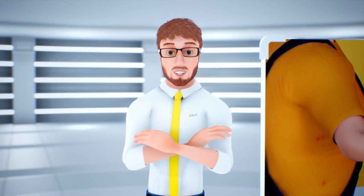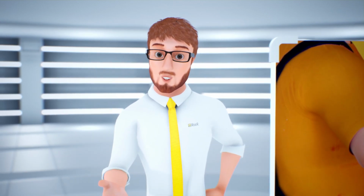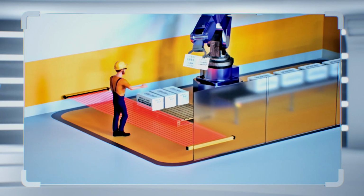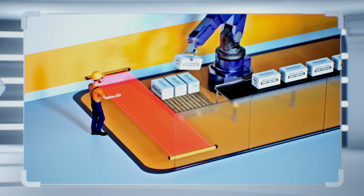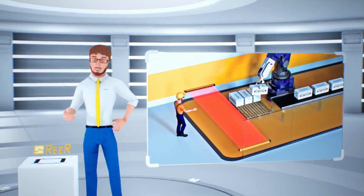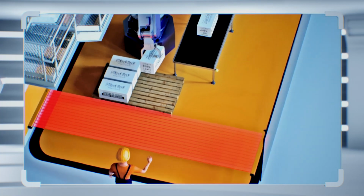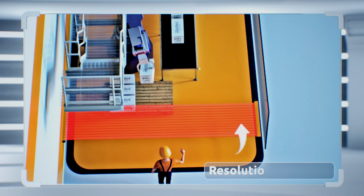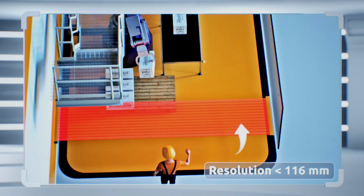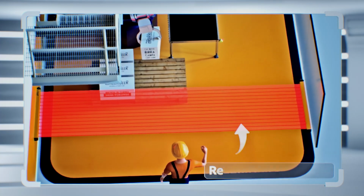When it is necessary to verify the operator's presence in a dangerous area, for example in front of a machinery, the light curtain is positioned horizontally, allowing for the continuous monitoring of a presence in that area. The resolution of the light curtains depends on the height of the detection plane, but cannot exceed 116 mm.